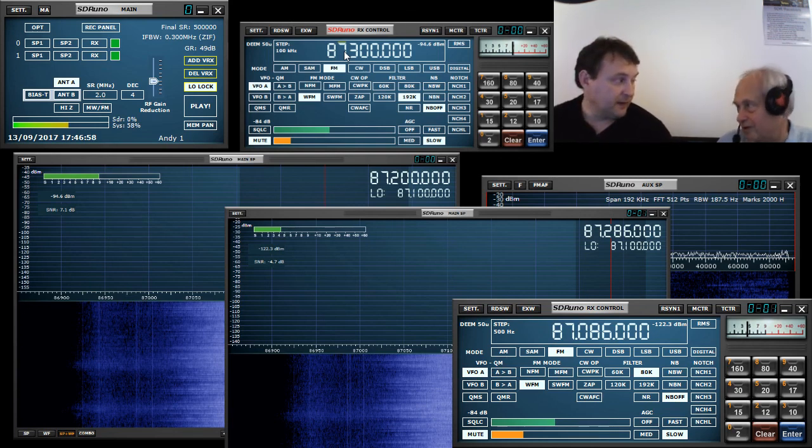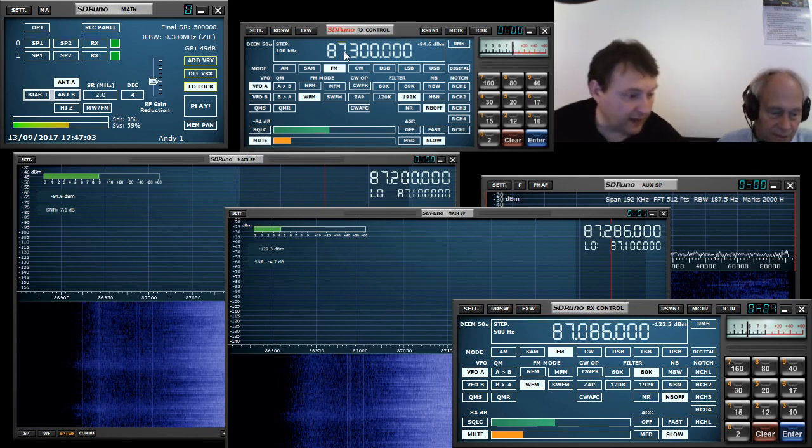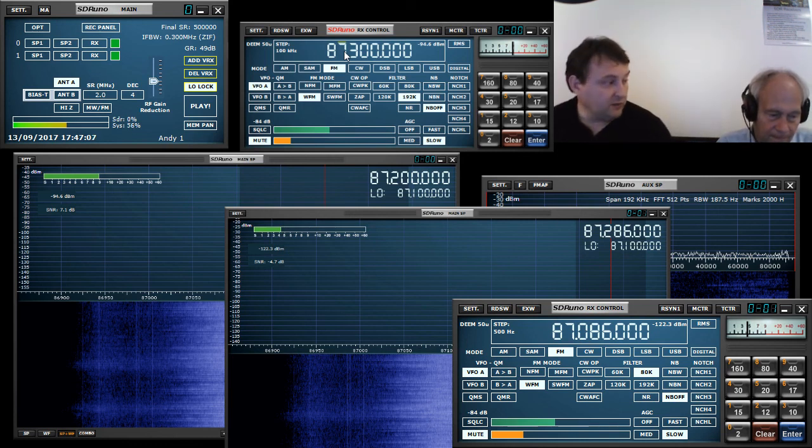Because you're under the 10 megahertz. You'd be within the bandwidth. In that case, if I set a LO frequency of 91 with a bandwidth of 6, then I would get all of those frequencies.